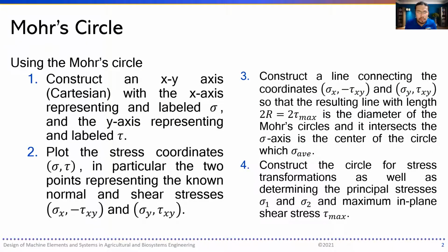Now, how is the Mohr circle constructed? So, the conic section properties of circles, there should be a Cartesian coordinate system, and we let the x-axis be the normal stress, and the y-axis, representing the shear stress. To create now the circle, there has to be 2 points, and these 2 points will be the endpoints of the line that forms the diameter of the circle.